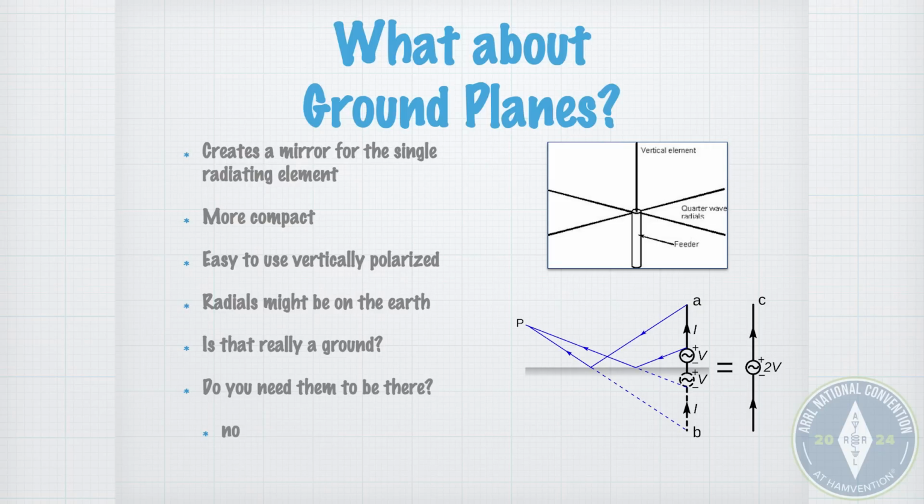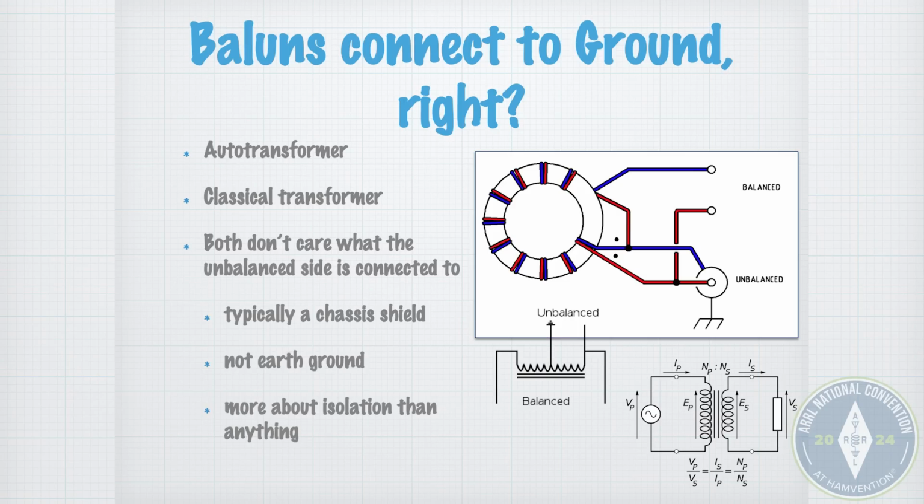Now, balun, right? The whole idea with a balun is it connects to ground, or let's just say the chassis of your radio. But baluns aren't really mystical devices. They're transformers. And like I mentioned earlier about the split phase in your home, they decouple the voltage references, and you can recouple them in a way that you want.